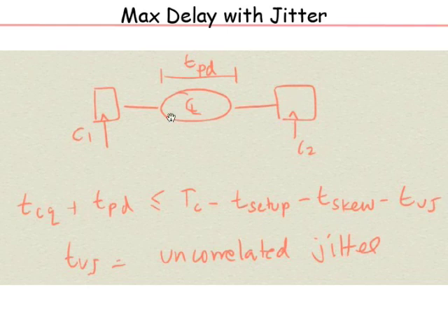The data for the other is being taken from other data. So if that is uncorrelated with this, then it will be a problem. You have to take that into account. In this kind of analysis, you look at pairs. You have to do timing analysis for every source and sink. Data is also jittered because data which is launched from the clock is synchronous with the clock edge, right?